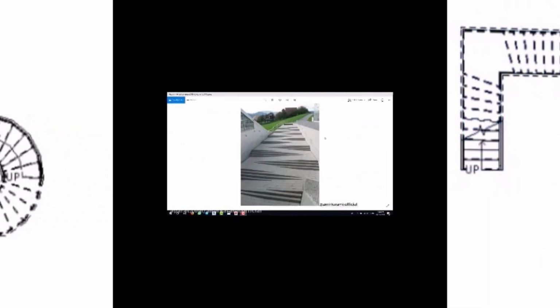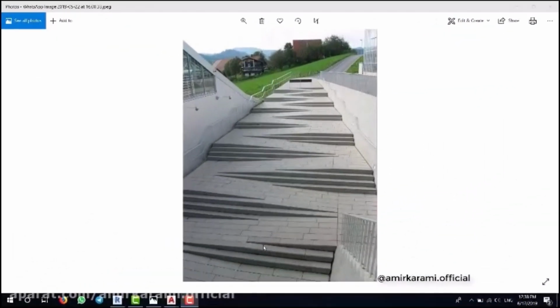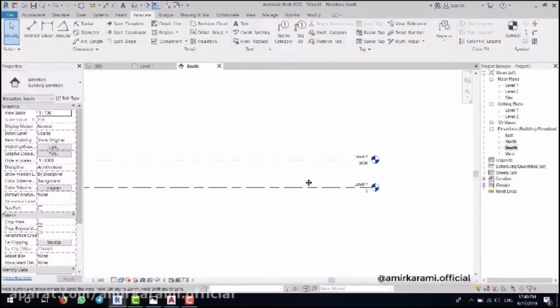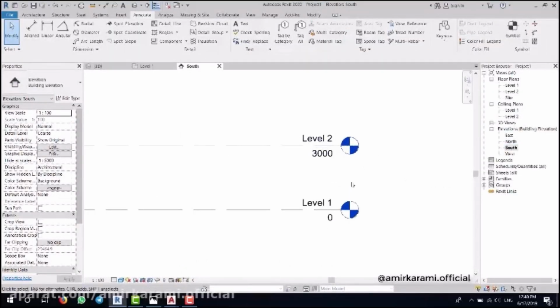our own. In this practice, we are going to model this image, which is a combination of stairs and a ramp. To kick things off, we need to form some hypotheses. Imagine that we want to go high 3 meters using 10 ramps, each 7%. And these stairs, the tread is 30 centimeters and the height is 15 centimeters. So let's kick things off.